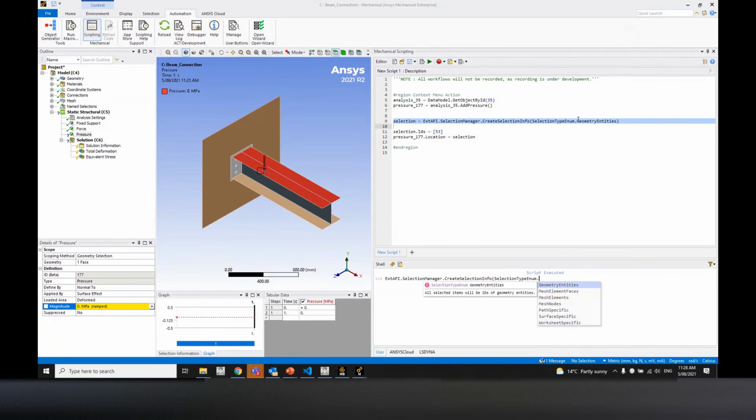What this does, in my head at least, to simplify it for everyone else, is just filter whatever you're choosing. After you choose the filter, you want to actually pick what you want to pick. In this case, I picked a face which has a reference ID of 53. How do I know it has a 53 reference ID? So let me show that as well.